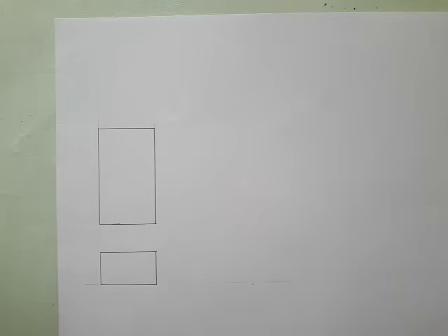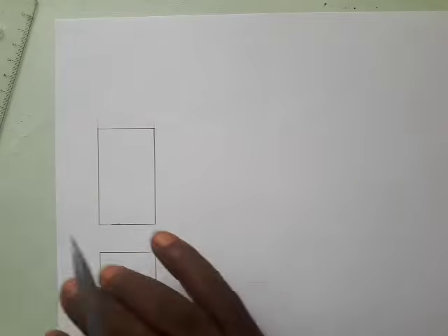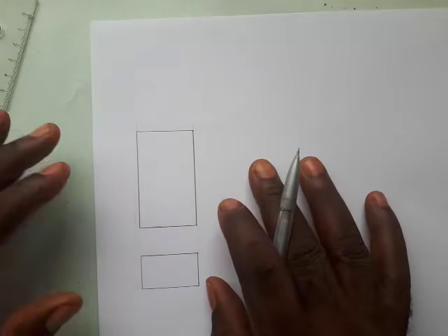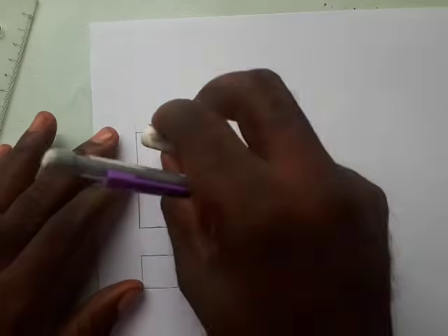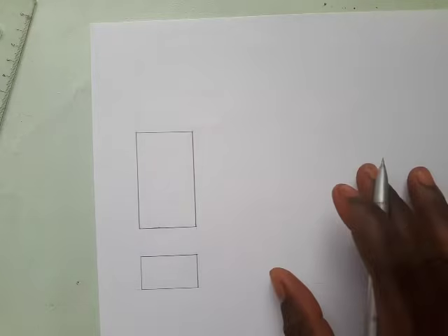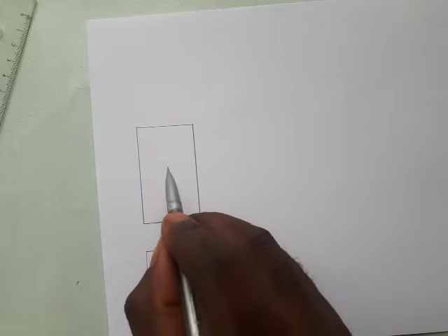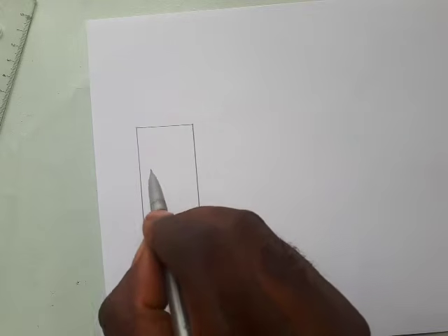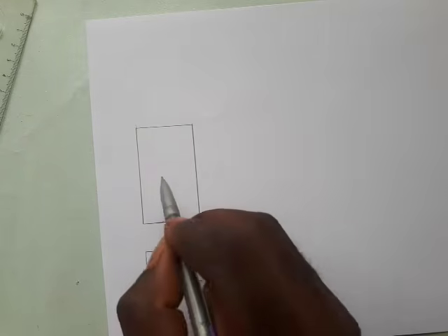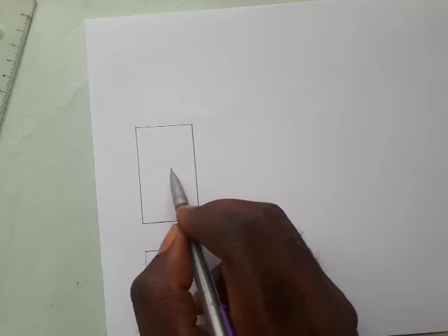All right, so now I'm going to show you a method that you will be able to apply to unraveling any question that has to do with auxiliary. Okay, so peradventure you are used to a certain method, no problem, but you can add this to what you know. So what you do first is try and define this object, the elevation, and transfer same to the plan. You may as well start with the plan and transfer same to the elevation. So you define it.